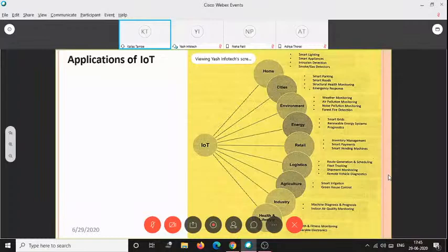To keep sensing the strength of that steel material and the cement, sensors are available at the time of pouring all these materials. If you put the sensors inside, including the supply and many other things we have to take care of, the sensors start sensing the strength over a period of time.